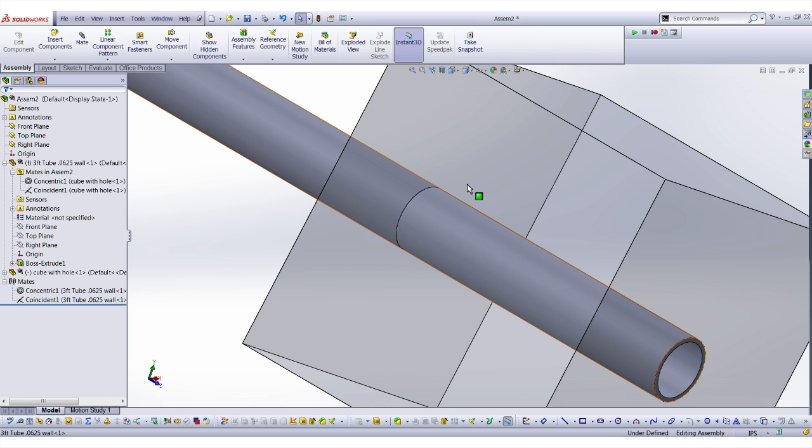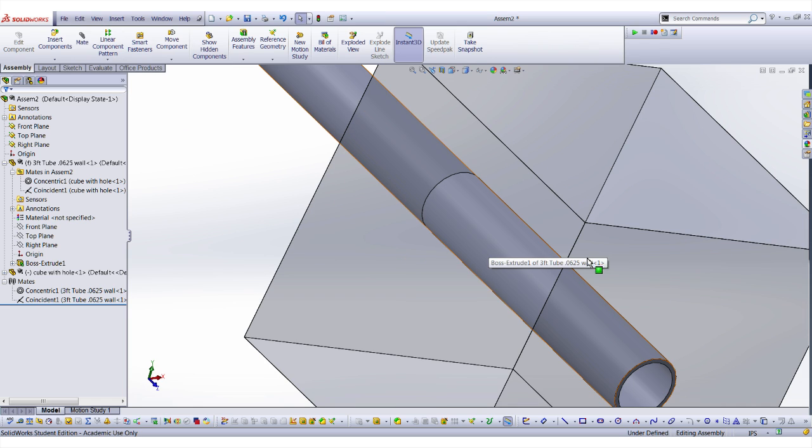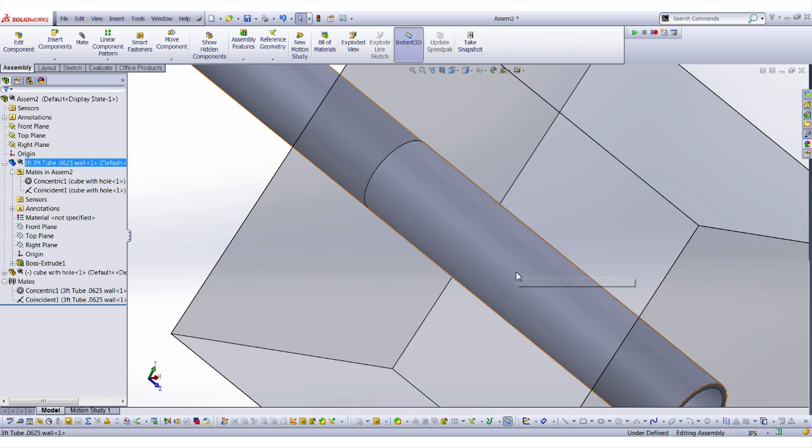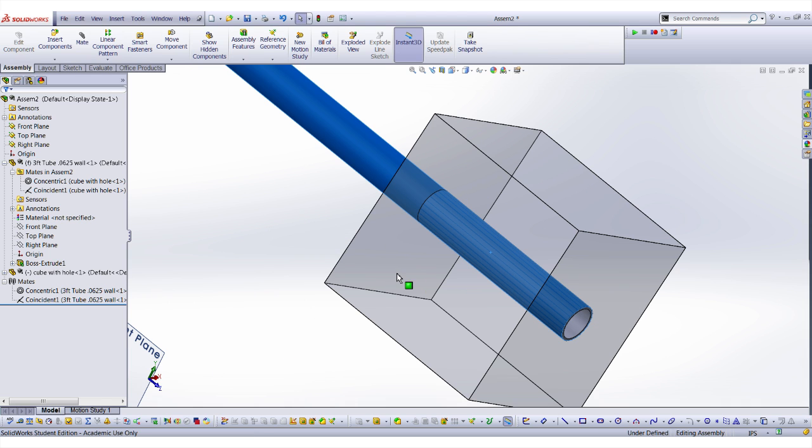One of the more important things to remember, and this is one that a lot of people don't learn pretty early on in SolidWorks and they get really frustrated: if you have a transparent object, if you click on something through it, it'll always click straight through the transparent object to that background thing. If there's not something in the background, it will click on the transparent object. But the other way to force it to click on the foreground object, the transparent one, is to hold the shift key. And that'll actually get really, really useful down the road.